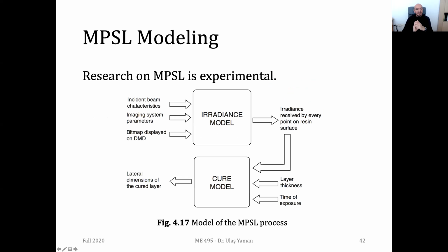So in this MPSL modeling, they have two separate portions. The first part is about irradiance modeling, related to the projector they are using. And the second one is somehow similar to the SLA. We are curing the photopolymers. So the fundamentals are exactly the same as the SLA, but this part is a bit different since we are not using a laser, we are using the projector itself. So you need to modify this part, but you may use the same model as the SLA process.